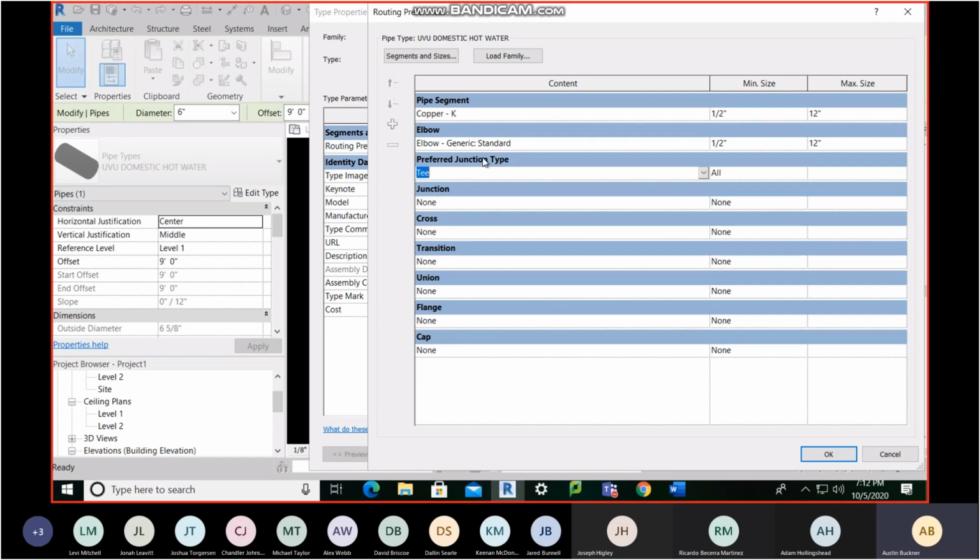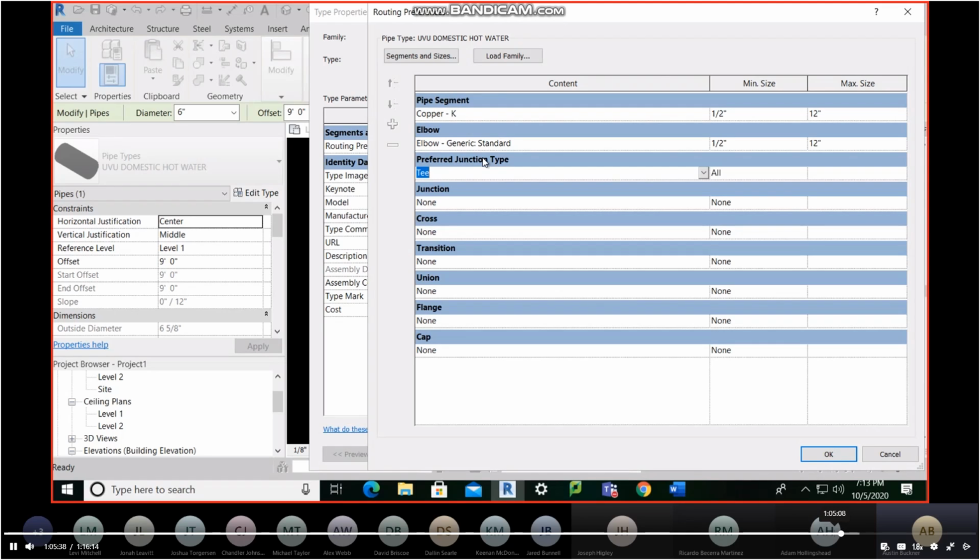So tap is basically, so T, it looks like this, right? Out of your T fitting. A tap is usually you'll have your pipe come in here, pipe in here, right? Usually a tap, they can be fairly big, but usually it's right on the actual line itself. So if I were drawing a section cut of my pipe, this would be my pipe, and I'd have just a little piece that just kind of comes in the pipe. It's not a fitting, or this is a fitting, but it taps into your actual pipe. And what it allows you to do is just get tighter groupings together. Usually it's on steel pipe, because they'll take the actual steel, cut it with a welder, and they'll throw this, it's called a nipple, inside of it and then weld around it. It's cheaper, but it still gets the same point across.